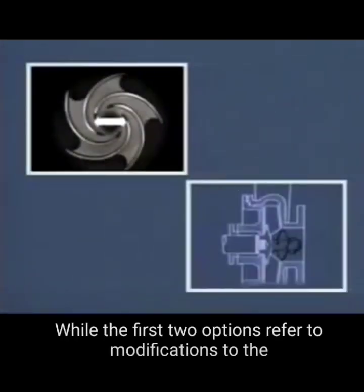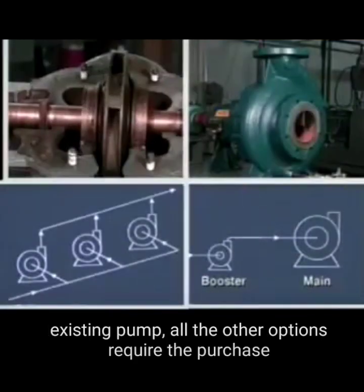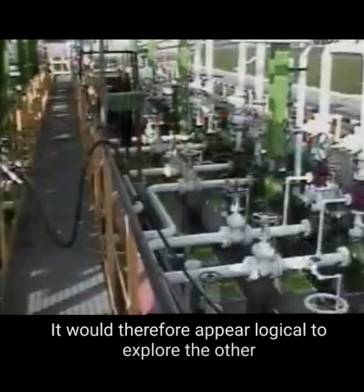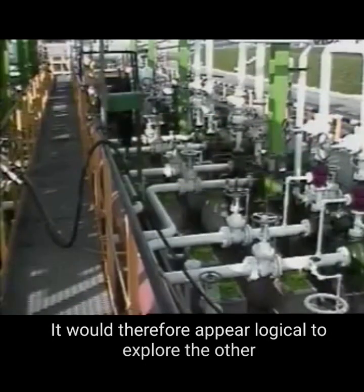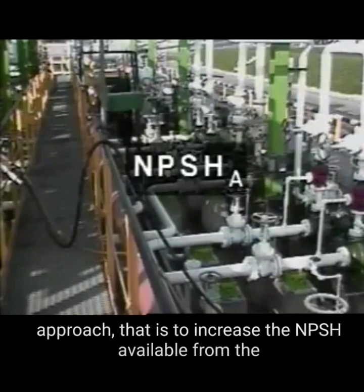While the first two options refer to modifications to the existing pump, all the other options require the purchase of at least one new pump. It would therefore appear logical to explore the other approach, that is, to increase the NPSH available from the system.